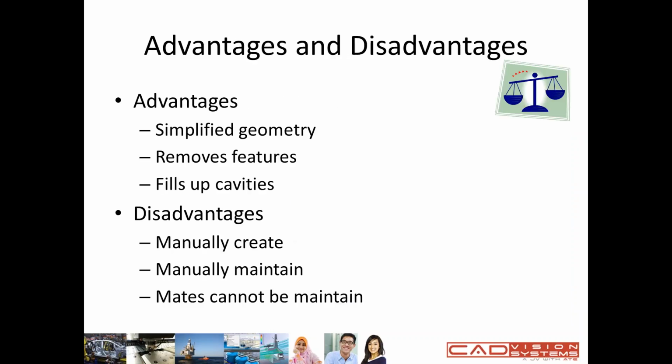Okay. So now we come to the advantages and disadvantages of defeature. About the advantage, it simplifies the geometry. You remove the features and also fill up the cavity. And going to the disadvantage, in defeature, basically you have to manually create it, and it cannot be maintained automatically. You have to maintain it.